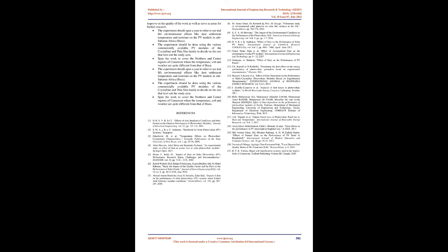For conclusion. The effect of dust on the performance of a PV module was investigated in an indoor experimental setup at different mass deposition using transparent sheets. The output power, hence efficiency of the module, was significantly affected by the dust deposition density on the module surface. The clear sheet was found to have little effect on the module's performance. We got the maximum efficiency 6.6%, minimum 5% without dust, and maximum efficiency 5.3%, minimum 2.1% with dust. The result shows that dust considerably reduces the power production by 58% and efficiency by 58%.